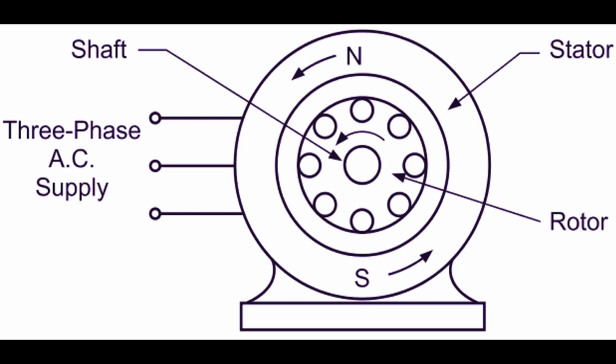Battery charging. Another important aspect of voltage regulation is battery charging. The voltage regulator monitors the state of charge of the battery and adjusts the alternator's output voltage accordingly. When the battery is low on charge, the regulator increases the field current to produce a higher charging voltage. As the battery becomes fully charged, the regulator reduces the field current to avoid overcharging.